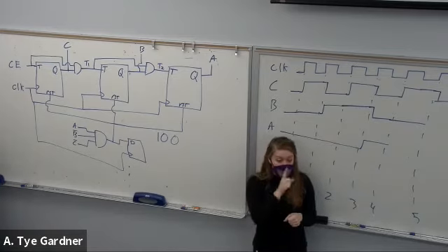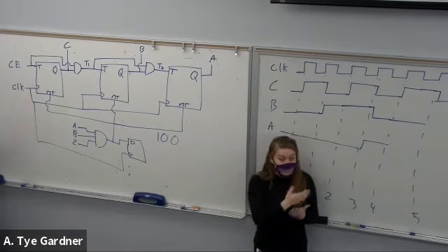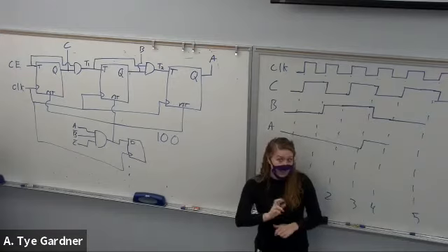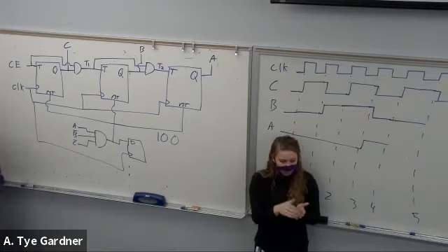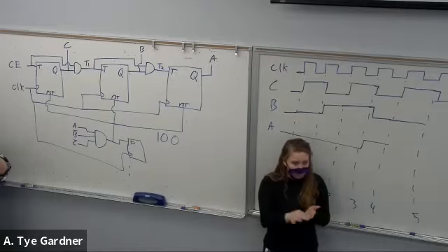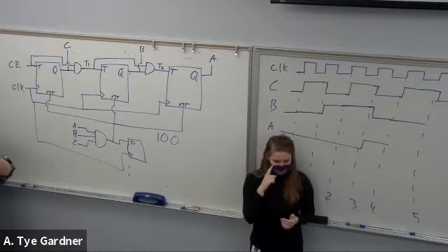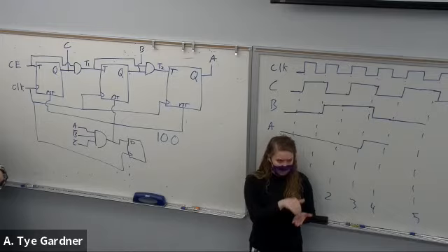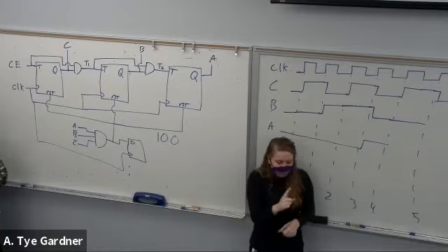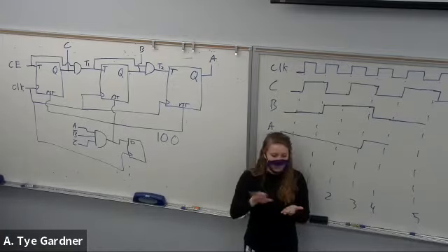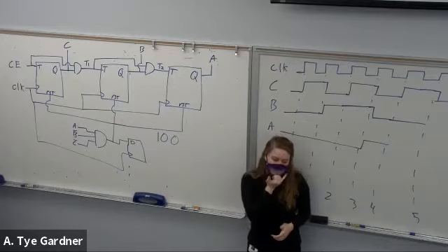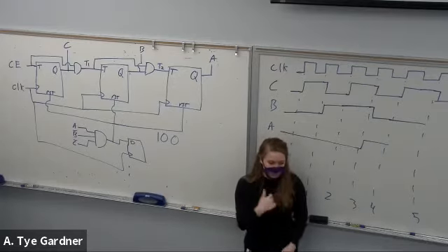Yeah, so good question. Make sure when you're doing it, because sometimes we'll make assumptions in the digital logic about when to do that reset, and it's common to make that mistake. And it's really hard, because a lot of times your counters will be like 1,000 or 10,000, and you're like, well, should it be 10,000 or 9,999? And looking at a timing diagram to get that kind of 0.01% error accuracy is hard to do. So beware of your counts. I may have screwed it up. Well, I did screw it up the first time, so don't feel bad if you do. We'll learn it and practice it.